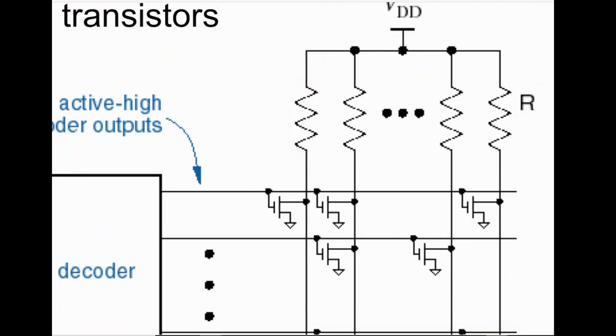So in terms of energy efficiency, it's not the best option, which is the reason why we talked about using PMOS transistors in the pull-up network. Right now we are just showing that resistors are there in the pull-up network, but it's not the best way to do things. Instead, if you were to use PMOS transistors in the pull-up network to go to VDD, that would save you a lot of energy. So in terms of energy efficiency, that would be better.